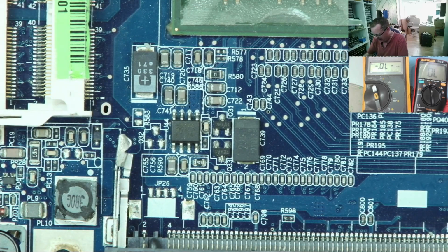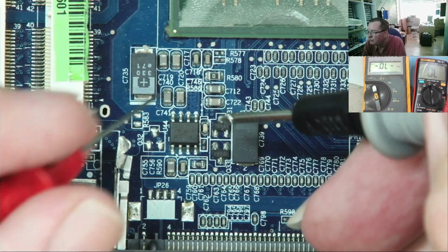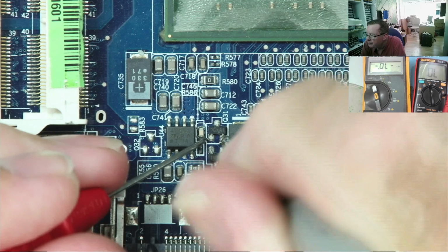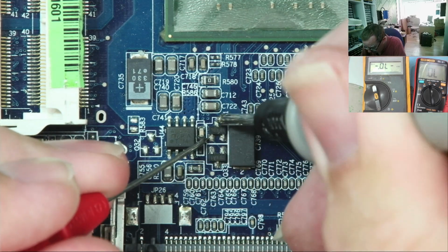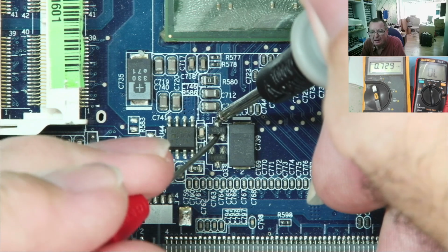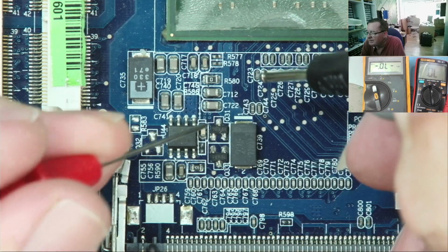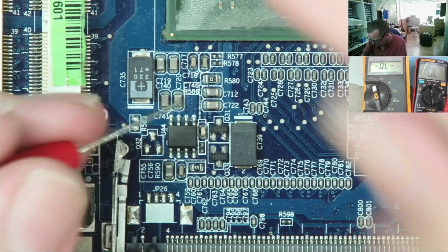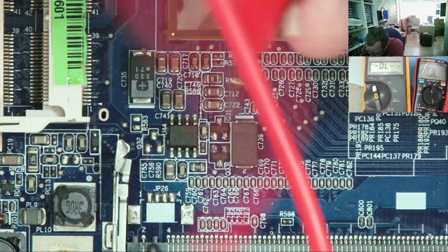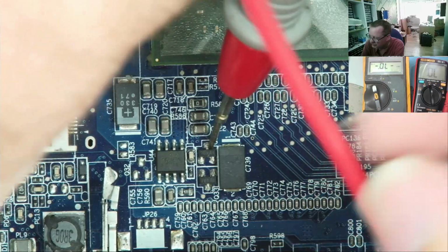Now, if we have a look at a MOSFET again, we were looking at some before, there's one here. So you can see that this one reads open. That reads open. If we go to here, we see a parasitic diode. So this is a MOSFET, and we can test the MOSFET. To do that, you need three hands, but I haven't evolved the third one just yet. So it is just about possible to do it with two hands.